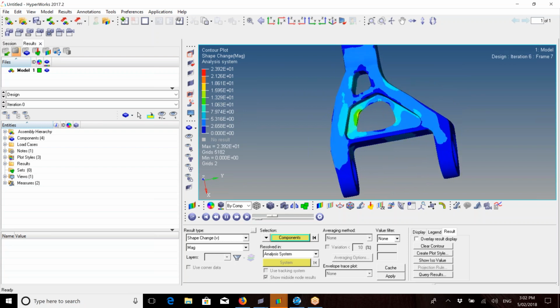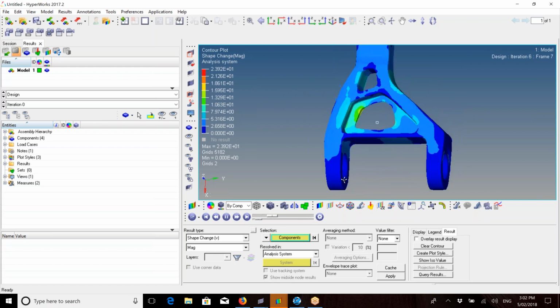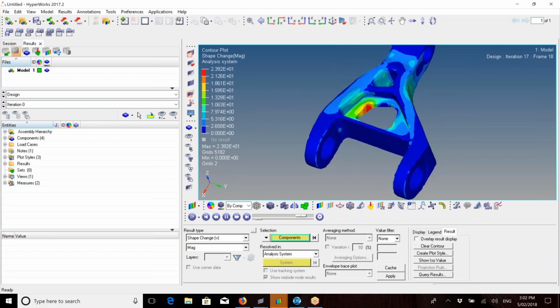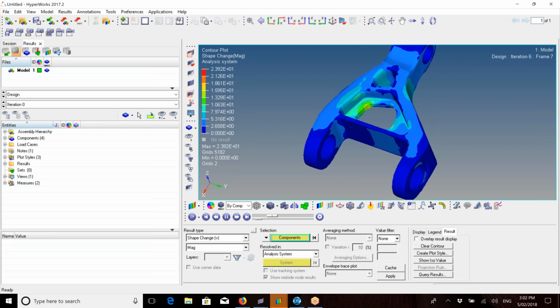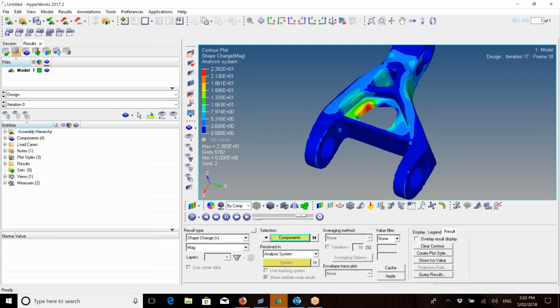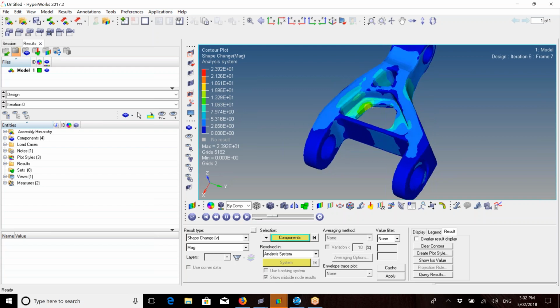So this has got to add material because it was so far in yield, although we've told it to minimize mass. So it's a thing to remember that, yeah, minimizing mass, you want it to be the lightest possible, but for all the constraints that you put in, it creates the objective for that case. So for our case, to get the stresses underneath 240 megapascals and to minimize mass, it's actually got to take some material from somewhere.